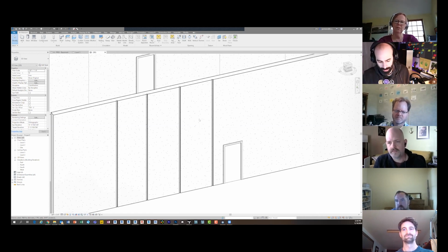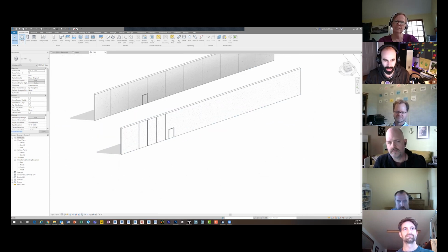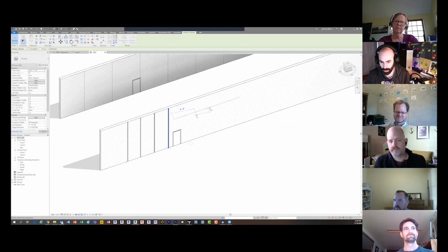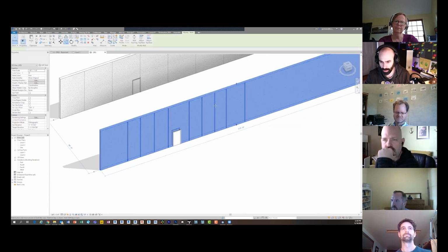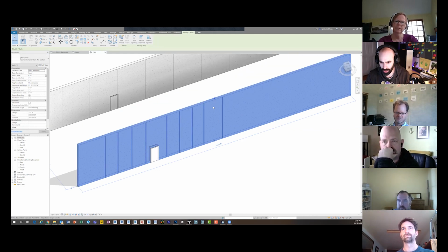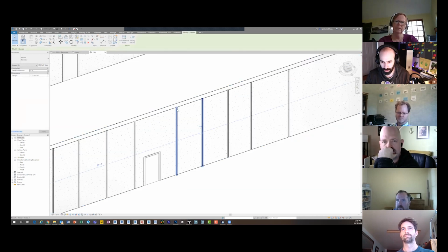That way you can do a nice grid pattern and all of that. So technically no, but what you could do, so that's the reveal option. So this is option sort of number 2, and as you can see, it works, and the reveals will go with the wall, I believe, right? So when we do the angle, you'll see it'll work fine. But as you can see, you're managing individual reveals on their own.